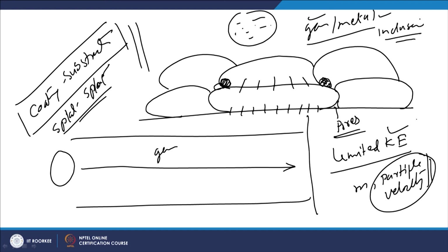So, the flight or the movement of the powder particles through the heat source should be for a shorter period, and in this regard the spacing that is called standoff distance, the distance between the nozzle and the workpiece surface or the substrate surface, has to be optimized, not too very short, not too very long.